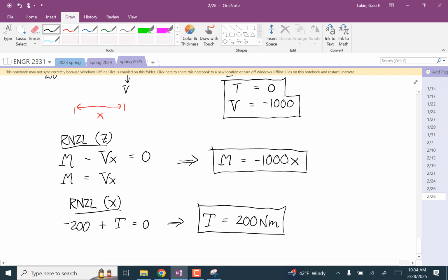Is that pretty normal for twisting something where it's constant across the entire thing? Yeah, because we won't have any distributed load torques. We'll never have anything other than that. It's hard to even really imagine how that would come about. Well, actually, I could imagine how it would. If you have a distributed load acting that's not acting along the centroid, then it's going to give you a distributed torque. But we won't have any problems like that. Wrenches on a super long octagonal rod, like one at the end and one at the halfway point.